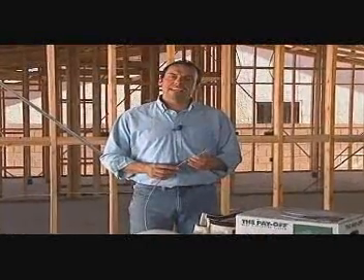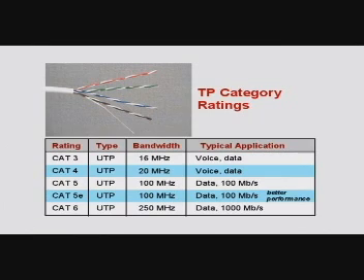In order to handle high data rates, newer high-performance TP cable called category-rated cable should be used. Category ratings were established by the Telecommunications Industry Association to standardize performance ratings of cable and equipment. The ratings give the minimum performance requirements for attenuation, resistance, interference between pairs, and so on. Category ratings start at Category 3.